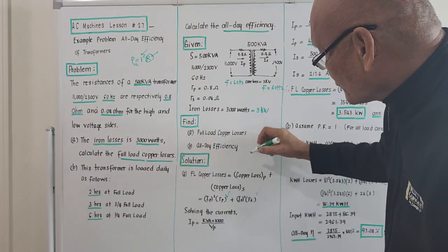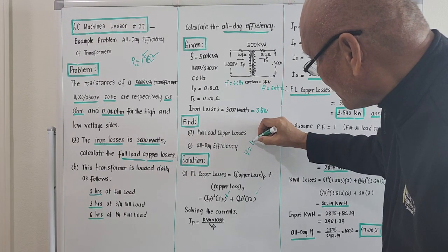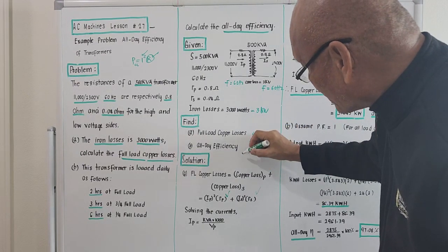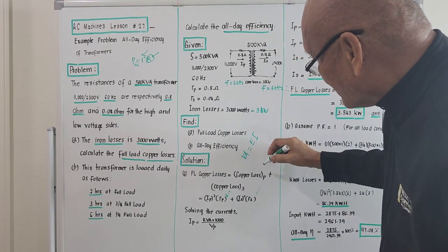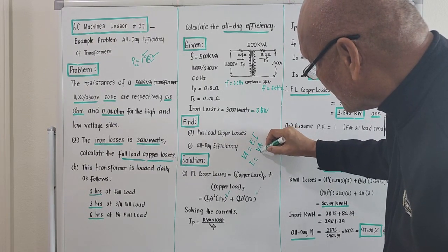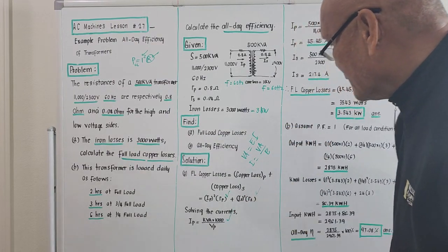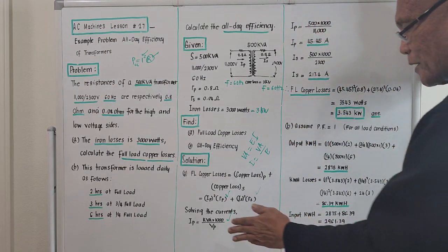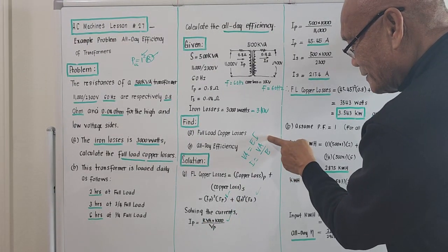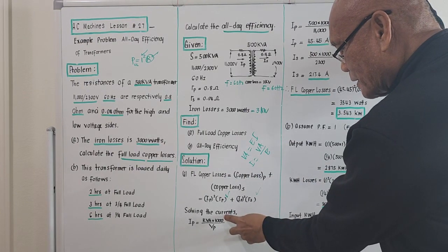We got this equation from the equation volt ampere is equal to the product of E and I, right? So if we compute for I, it should be volt ampere over E. The given apparent power is kVA, so we must convert it to VA. So there is a multiplier 1,000 over here.